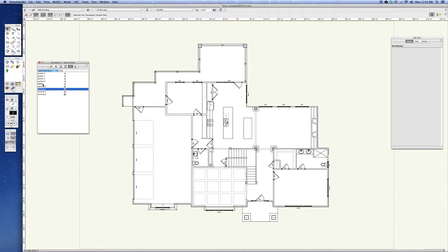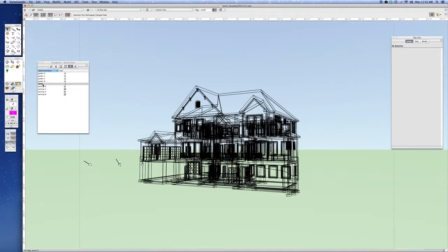And lastly, it would just be the model. Lots of times if I'm modeling something and I want to just see a quick model, I already have this saved view. Double click it. It just brings up a wireframe view of all of these linked layers, and then I can just use the flyover tool and the walkthrough tool and the translate view tool to get the view that I want, and then just pick which rendering mode I would like to use.